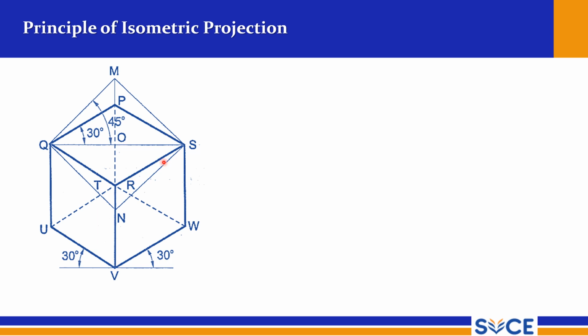So that is the isometric concept. The axes can be derived from this concept, where the diagonal of the cube is kept perpendicular to the ground. In that fashion, you will observe this view. It will look like a hexagon.